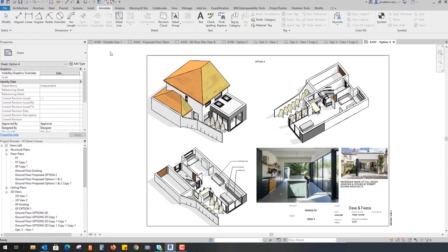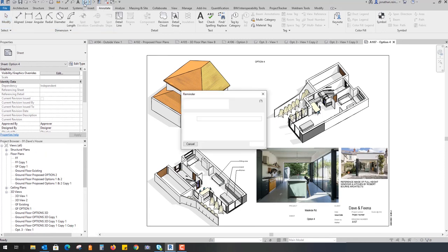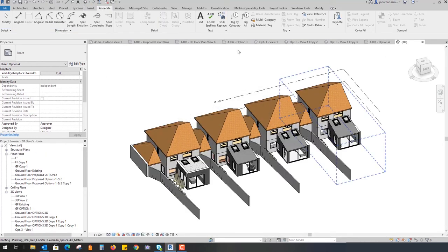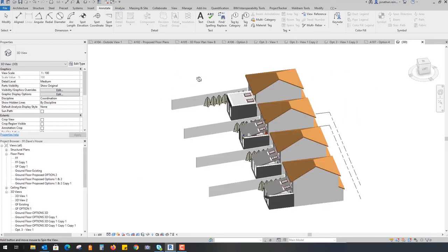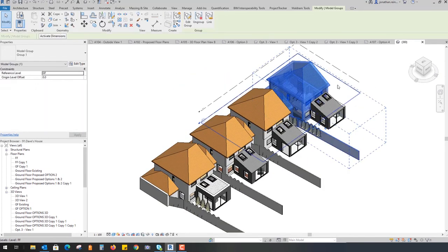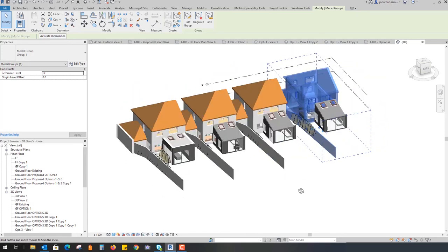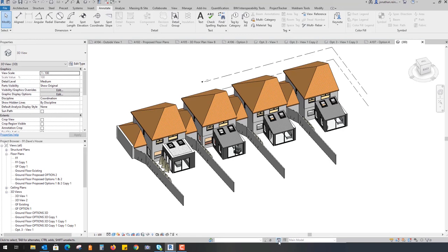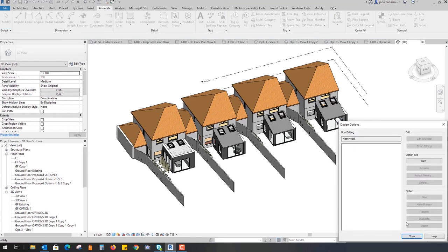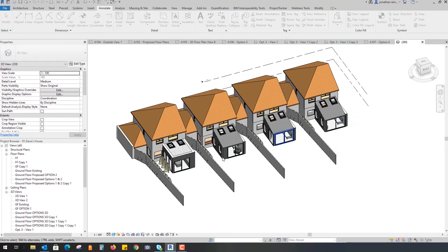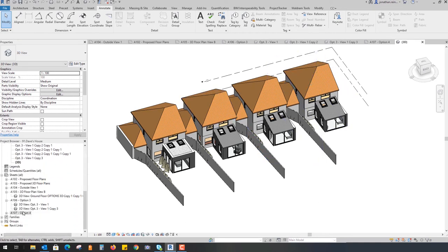So how this actually works if you go into your modeling environment, it's 3 separate buildings. The existing building is modeled as a group, so that's just duplicated all the way across. If the existing building changes, then these all update, and then all of the designs were just modeled separately as well. So again, I will say you can use design options to do something similar like this, but for this particular example, I just wanted to show it as a duplicated element across there as well.